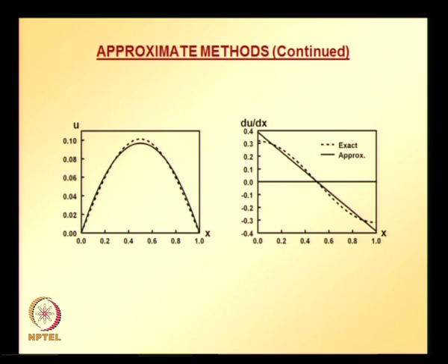So, that is why Galerkin method is superior to least square weighted residual method and collocation method. Please note that we put in the same amount of effort. We started with quadratic trial solution and still we got a better solution using Galerkin method. And if one wants to improve this solution that we just obtained using Galerkin method with quadratic trial solution, they can do it by selecting cubic, quartic or quintic polynomial as a trial solution.